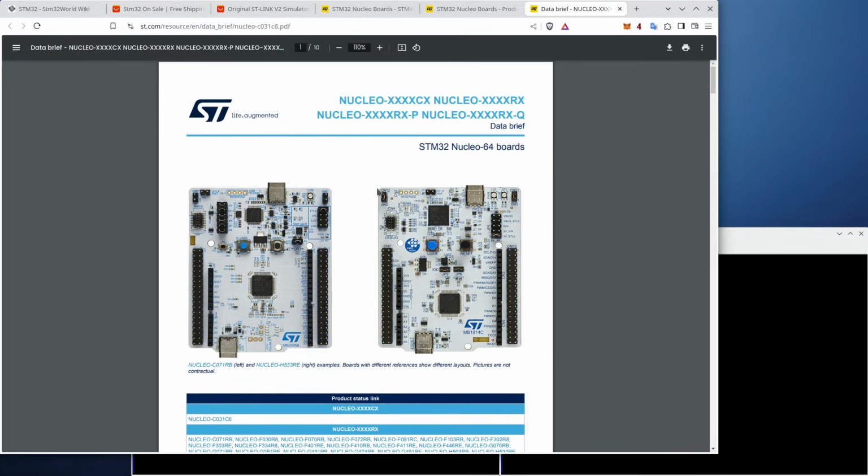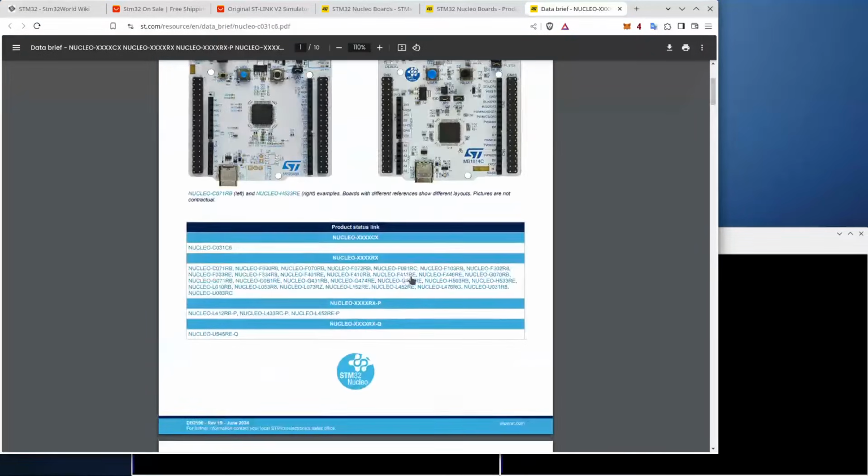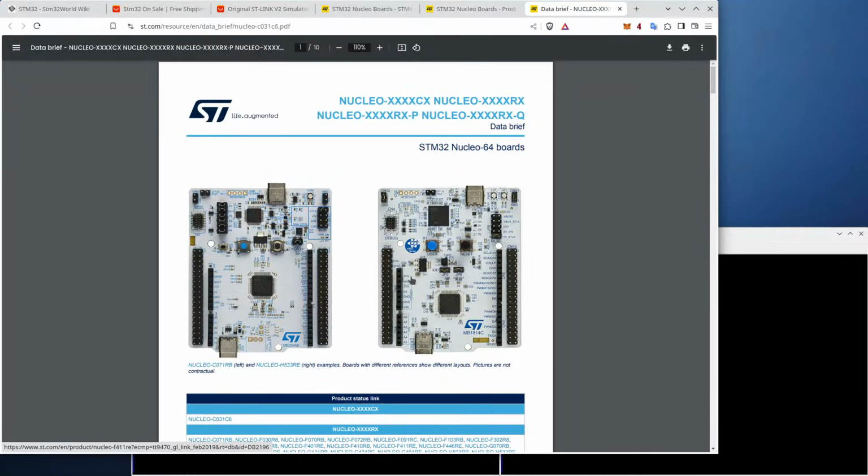There. You see that the top of the board is actually the ST-Link device, and at the bottom of the board you even have an Arduino header. You also have the straight-out pins, it's not standardized, but all the IO pins are pulled out to a header out here, so this would be a very, very good starting point. They are slightly more expensive. I think you can get them down to about $15 for one of these boards, and it's a very, very good starting point for development.